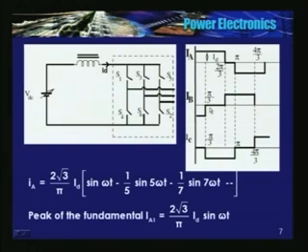See, at this point S6 turned off. In the upper leg, S1 is on, so one device has to turn on in the lower leg. S4 cannot, because S4 turns on at pi. So at this point S2 turned on.